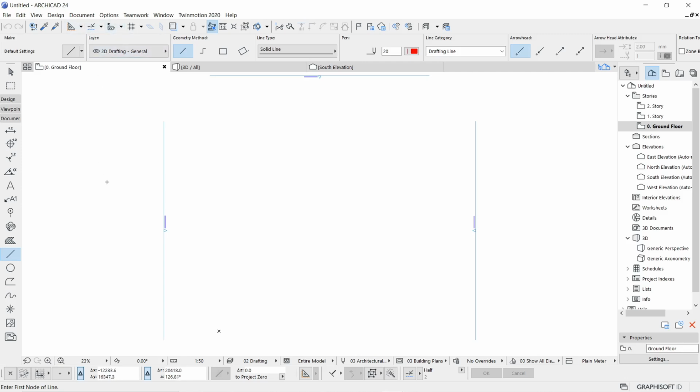Okay, and then at the bottom of my screen I can see there's an X, Y coordinate or R, A written in this coordinate palette. I can see there is one delta button. If you keep your mouse on that, it will be written as absolute slash relative. So whenever you keep the mouse on the delta button, it is either absolute or relative mode. So at present you are working with the relative mode because both the buttons are pressed. Okay, so what do you mean by relative and what do you mean by absolute, that I'm going to explain. So right now, first of all, let's switch them off and take them to the absolute method.